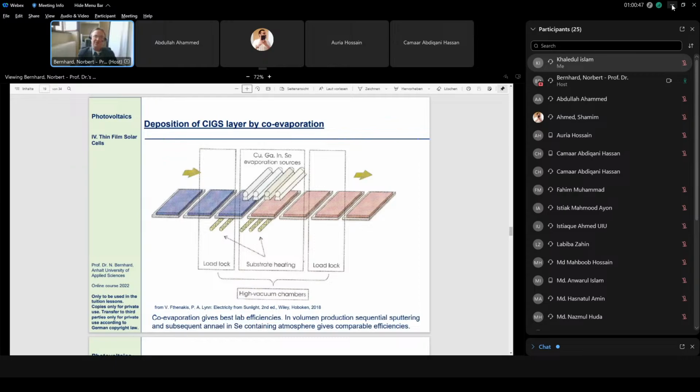And in principle, this picture shows us a principal concept. One side, usually with TCO, is the light incidence side. Then we have usually a metal back contact. I said already the EBL and HBL are optional. And this green and blue color are the two organic semiconductors, the electron acceptor and the electron donor. And what we see here, similar as we had it with the titanium oxide spheres, is a sort of blended concept. That means we don't have really layered structures, we have a blended structure. And the reason for this blended structure is to increase the interface very much.